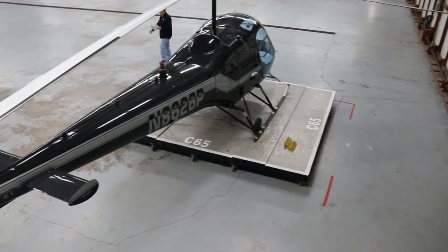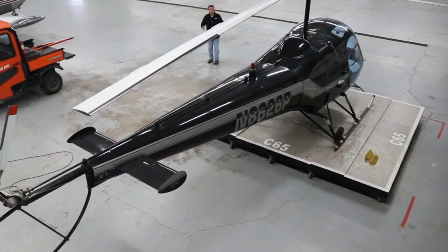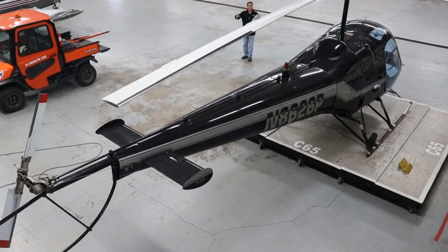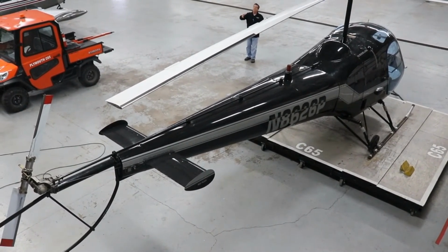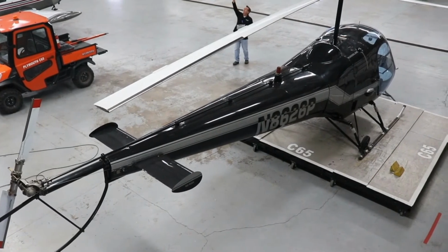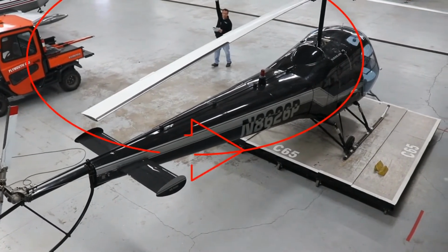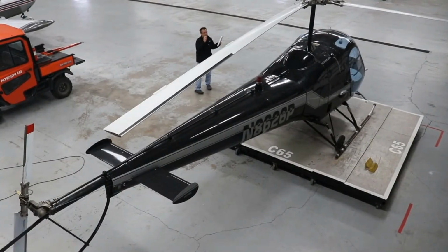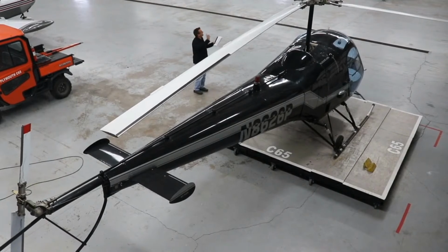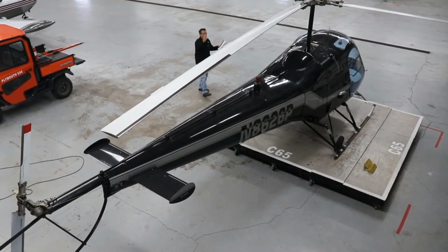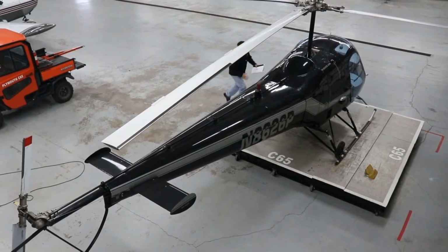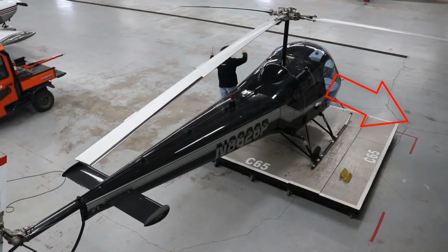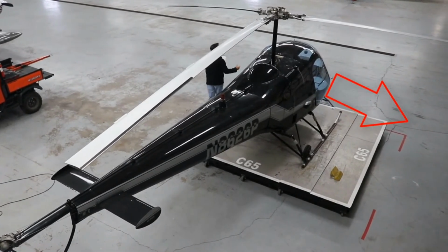So the first thing I want to point out is blade rotation. You've got to think about which aircraft you're flying, which aircraft you're talking about in your discussion about translating tendency or drift. We're using the Enstrom in this example. This is a counterclockwise system, right? So the blades are moving this way, and we have the engine and transmission driving the rotor system. As that rotor system is going counterclockwise, the torque wants the aircraft nose to go to the right. Blades are spinning this way, nose wants to go to the right. We can understand that, that makes sense.